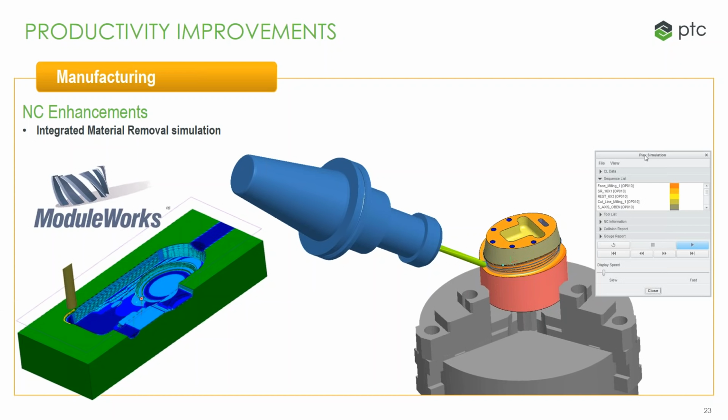You see it entirely inside the Creo viewport, and it fundamentally gives you a far better understanding and confidence of what the operation is going to leave you with before you start and cut physical metal. Whether you want to simply visualize a single toolpath or a complete operation. And we even provide you the ability to export out individual stock models or in-process stock models based upon a particular operation. Again, giving you more confidence before you physically cut metal.